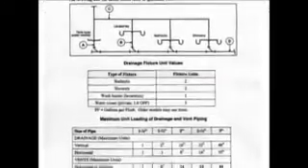Number 6, what is the minimum size pipe permitted at C? Let's take a look at the vent chart, which is the one on the bottom again. And we're looking at the last line in that chart, horizontal or vertical vents. We're going to need 10 units. So we have 1 in that first line, that's insufficient. 8 in the next line, no, we need 10. And the next line is 24. We only need 10, so 24 is more than enough.